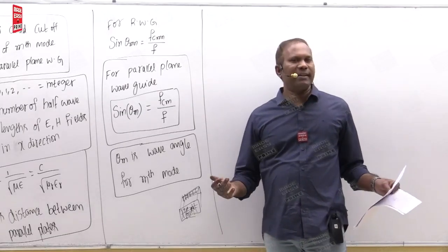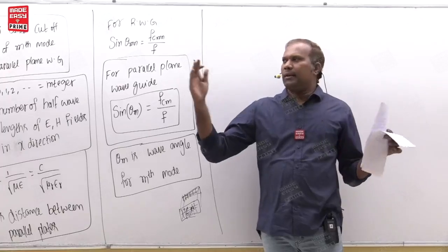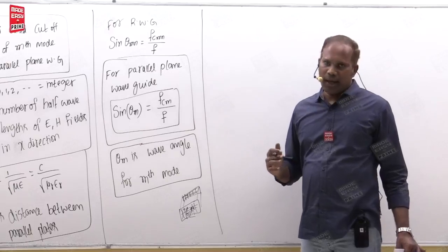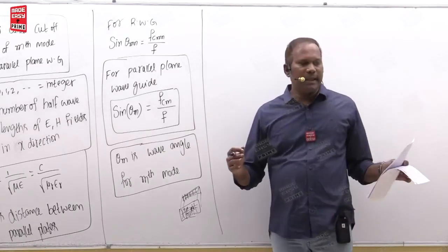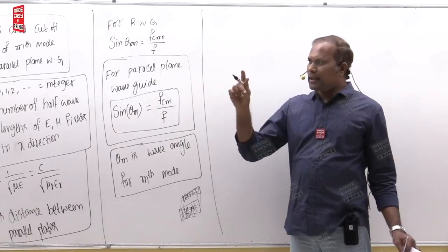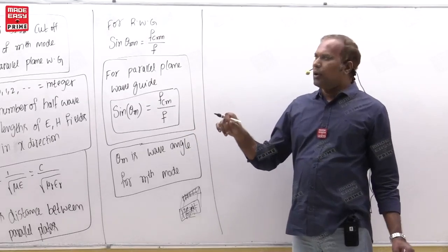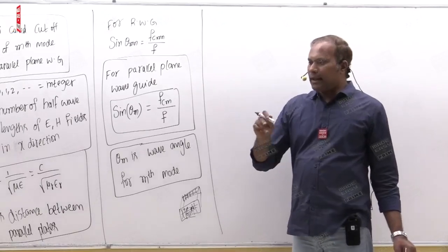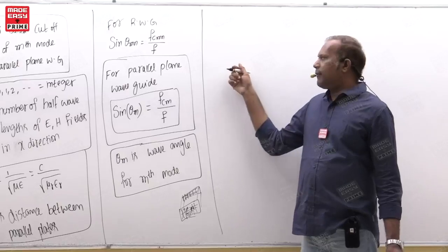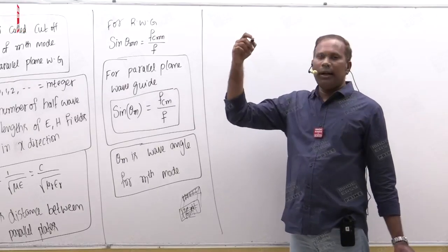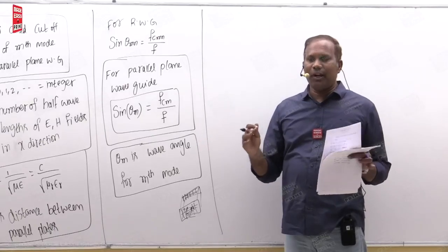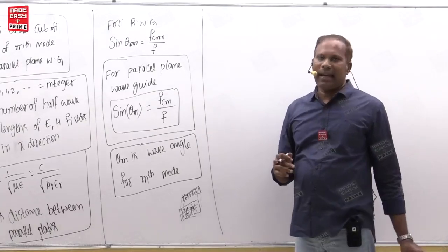आपके कमरा जैसा है वैसा ही है, वो 6 walls को conductor surface से manufacture किया हुआ है. Because for example, I am seeing this room here. Here air medium is there, in this epsilon mu is there, and now if EM energy hits this conductor wall, then it is reflected, again hits the top wall, it is reflected, so that it cannot go outside, it is confined. Confined means it is inside the rectangular cavity only.